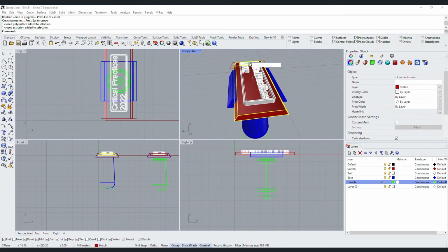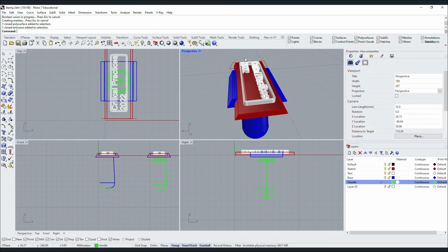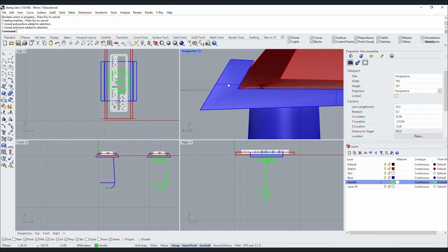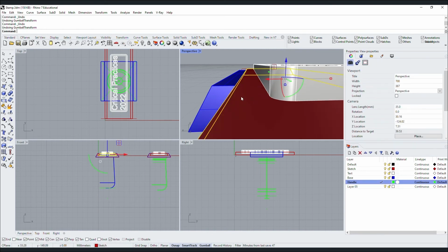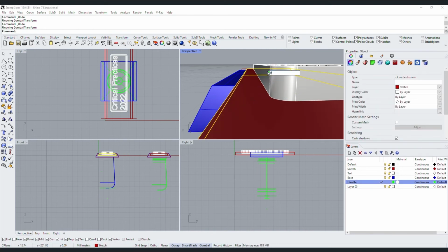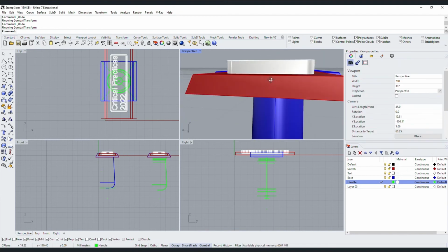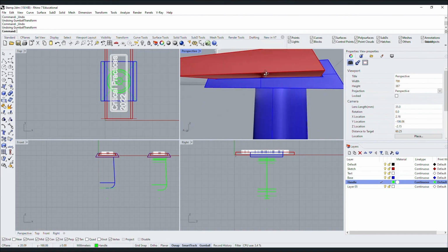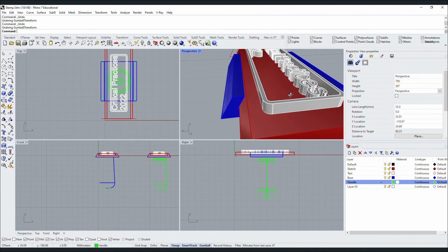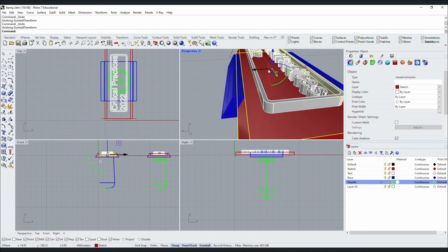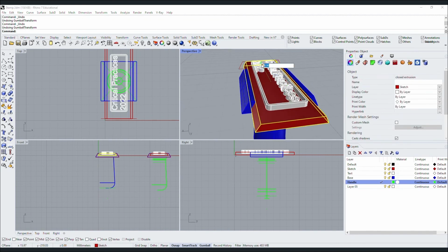Yeah, and now due to printing errors, we'll have a little margin of error. Scale it down to 0.98 so that it fits much better. And if we try to scale it further, let's see, I think it might be too much and it might slip out. So yeah, these are the margins of error. We need to print multiple times and understand what is the best margin of error. Then keep it as 0.98.